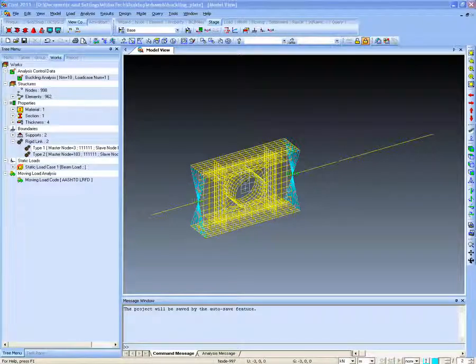Mr. Antino asked, can a frame element be switched to a plate element with any special function starting from the frame section definition? Sir, we can, as I showed in my presentation when I was modeling, you can extrude the node into a line element, and the line element can be extruded to generate the plate elements. So this is how you can do it.